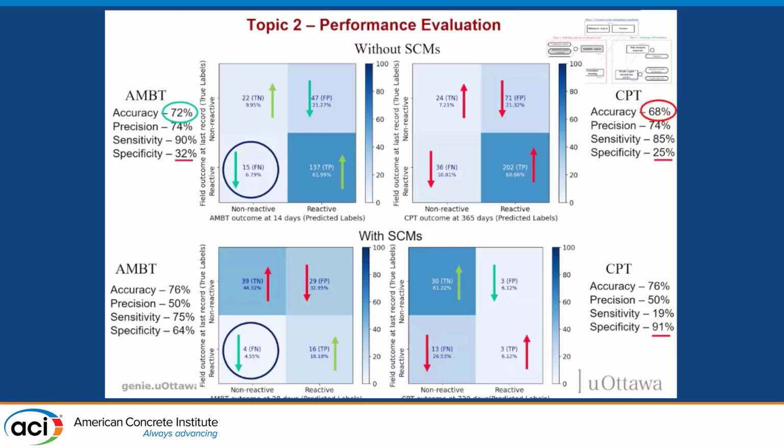So, it should be noticed that the aggregates used in this research are normally the aggregates that, for those that work in the AAR community, we call the aggregates that behave well. What does that mean? It means that our aggregates have very known behavior, we know what they should get in the accelerated test and so on, meaning that, based on experience, if we could get aggregates that are tested elsewhere, it could have been half of it. When we use SCMs, the precision is 50%, so you flip a coin, right? So we are really, really far from having a good test method, and we knew that.